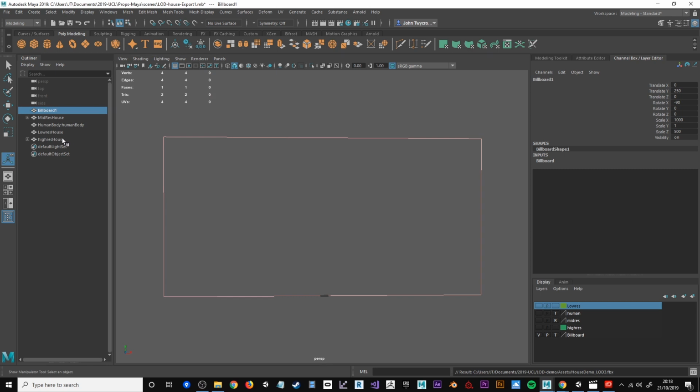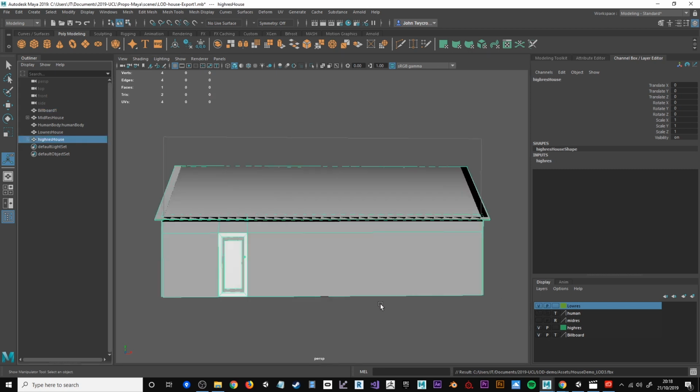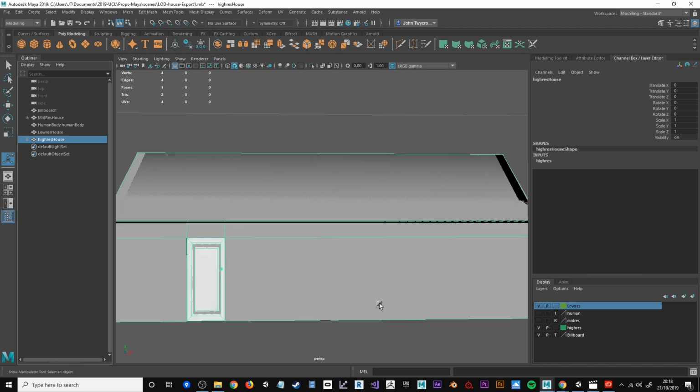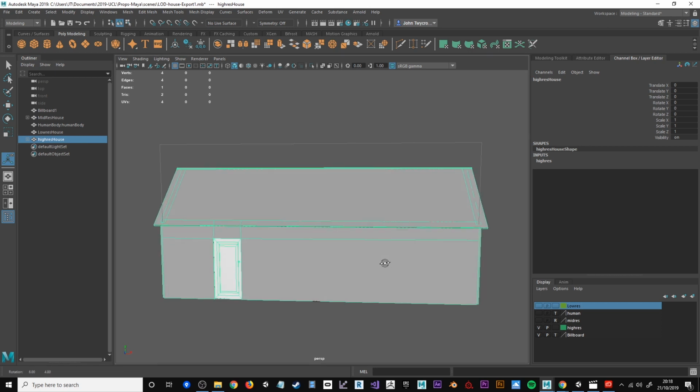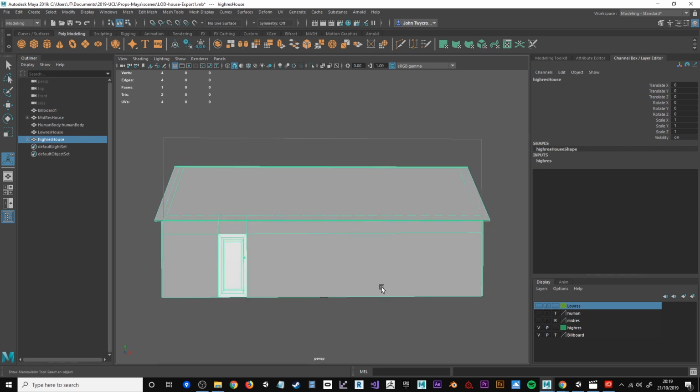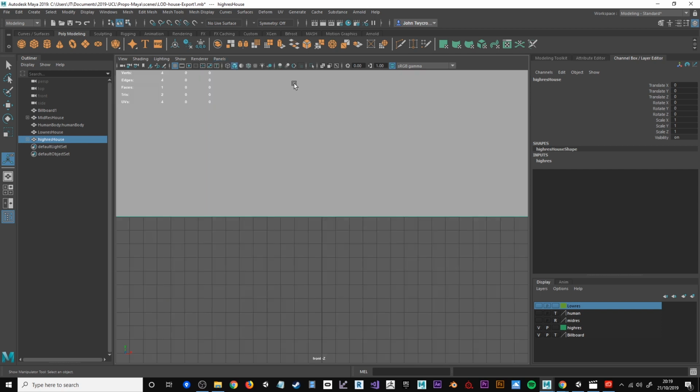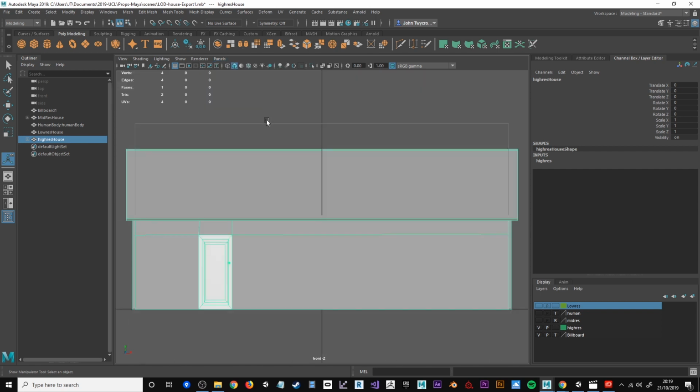Now, to finally get the image that I will project onto that final piece there, the billboard, I will actually go into a different view. I'll go to the front view. I can see that as a flat image there, and I will render this. So what I'm going to do is render current frame.